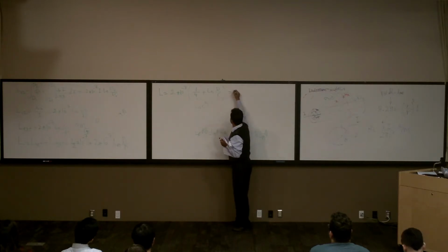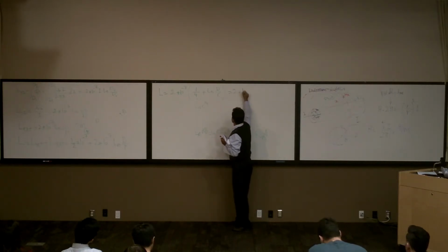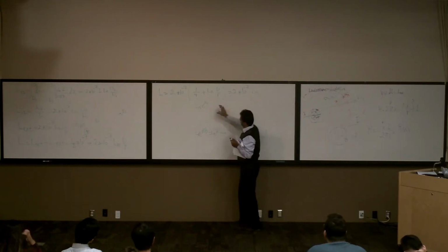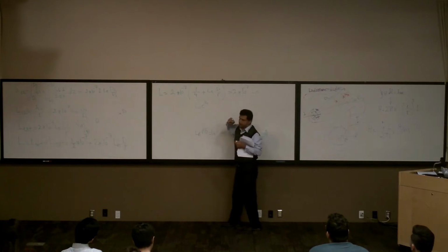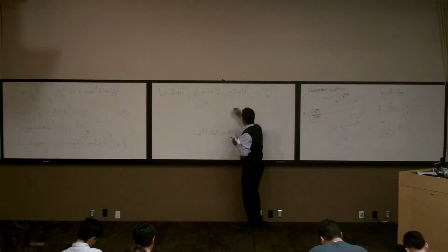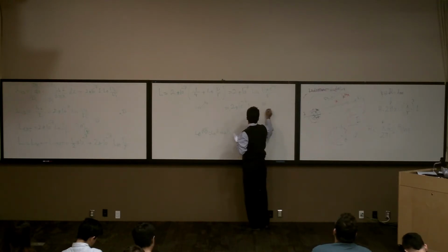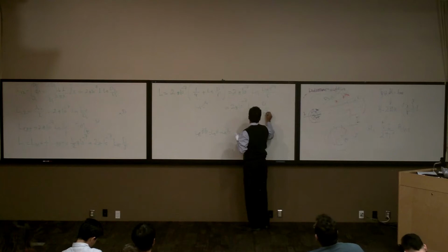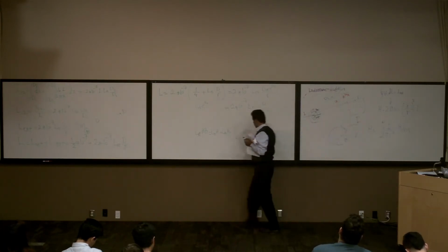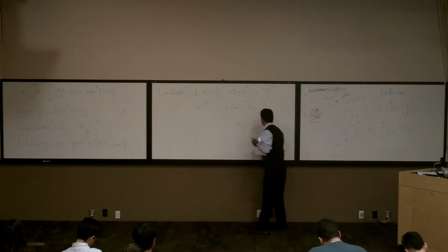So it's going to be 2 times 10 to the power of minus 7 times ln of this a times b, which is d times e to the power of 1 over 4, over r. Again, I'm going to write it like this: 2 times 10 to the power of minus 7 ln of d over r e to the minus 1 over 4.